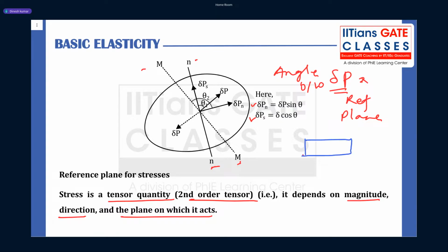When you have a tensile stress, yes, it is stretching out. Or in simple words, you can say this stress is going away from the section. Whenever your load is going away from the section, it will produce tensile stress, right? If you have a load which creates a stress which is coming towards the section, that is compressive stress, right? So it is not like your stress is going in the negative direction so it will be tensile. No, right? You have to see physically whether your load is stretching or compressing. Based on that, we decide whether your stress is tensile or compressive.